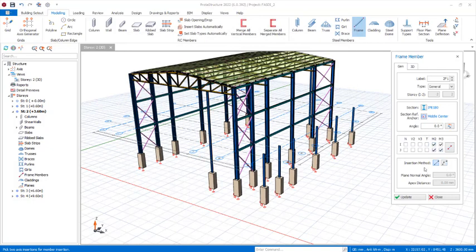We will be using the insertion method to be this one. This is the curve insertion method. Once you get that selected, you just have to come over here. The angle of rotation is going to be 90 degrees, and then we will have an apex distance of 130. This apex distance can be edited later.